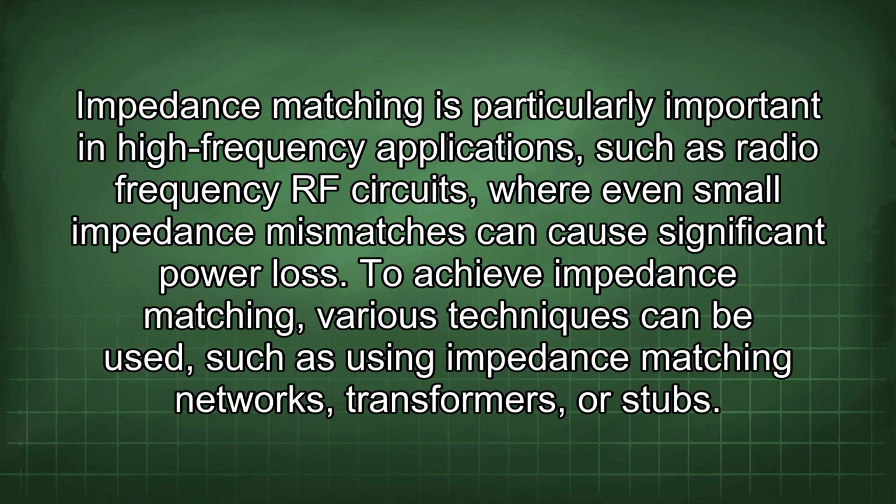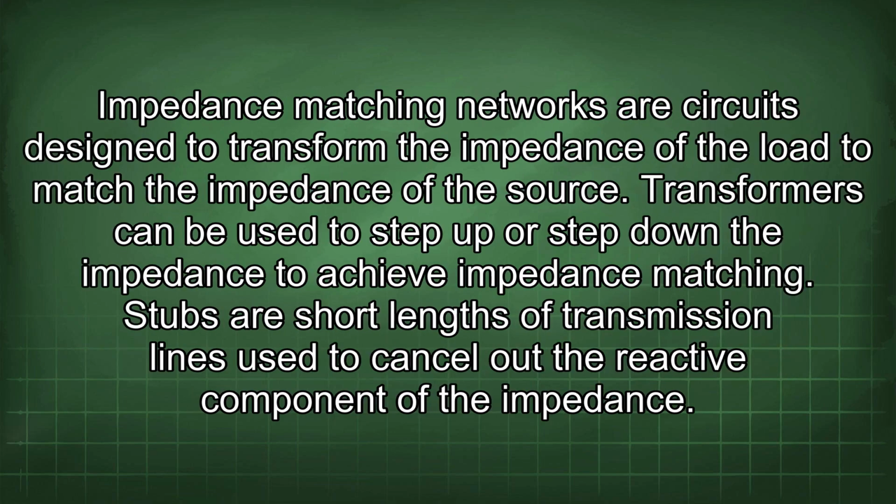To achieve impedance matching, various techniques can be used, such as using impedance matching networks, transformers, or stubs. Impedance matching networks are circuits designed to transform the impedance of the load to match the impedance of the source. Transformers can be used to step up or step down the impedance to achieve impedance matching.